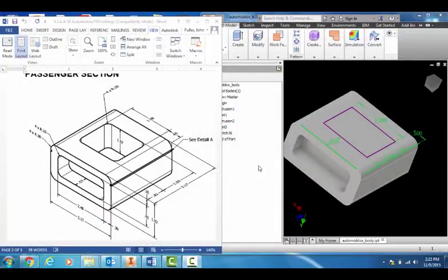Alright, so let's finish this hollow piece here. Notice from our assignment here, it has a depth of 1.07 inches. So we're going to have to extrude this in 1.07 inches, and we're going to have to give it 4 fillets with a radius of 0.2 inches. Okay, so let's do that now.